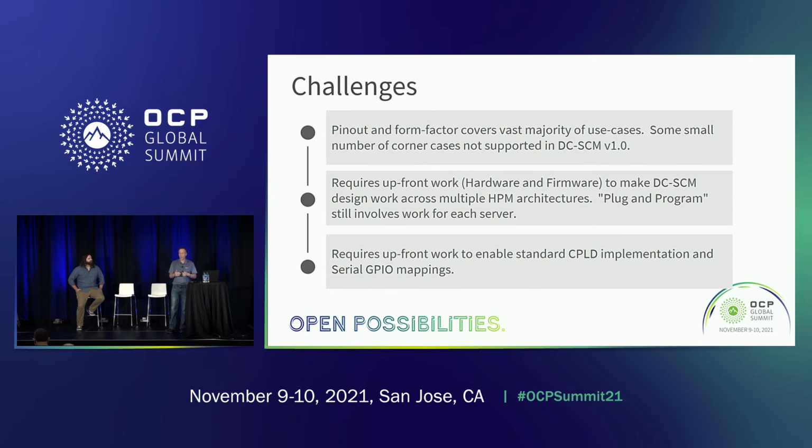We've got a lot of interest in it, but we're already looking at DC-SCM 2.0, in which we say, in the future we need greater virtualization because people are going to increase the number of UARTs, and they still want JTAG buses. All these buses take up lots of pins. So we're adding high-speed interfaces so that we can virtualize those and make ourselves even more future-proof.